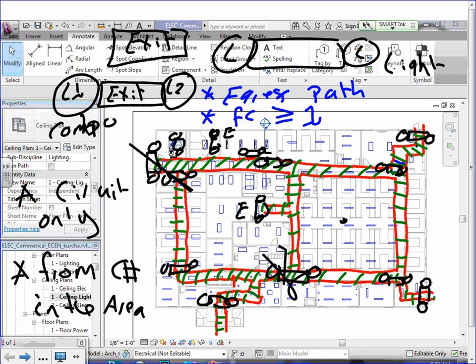So a lot of engineers and architects hate them because they look ugly. So next project, we will not use them. We will be using that fixture right above your head as an emergency fixture. But I want you guys to get into the habit of doing these bug eyes. They call them the cheapest, easiest way of having an emergency light in a commercial building, because they do not need a generator. We have a generator in the building. That's not an emergency generator. That's a backup generator.